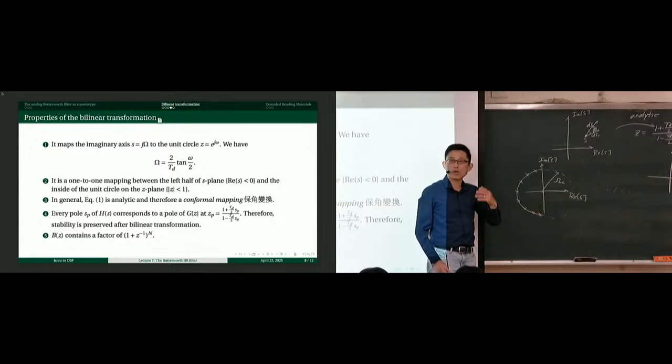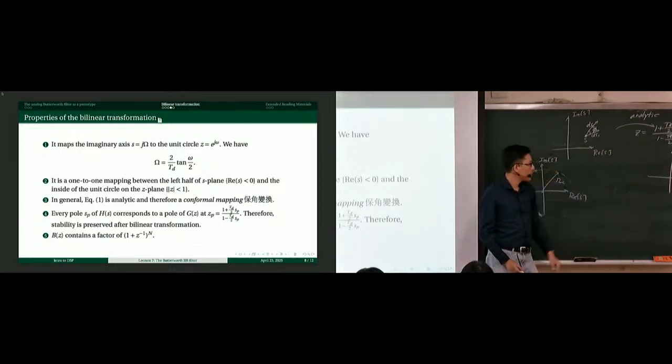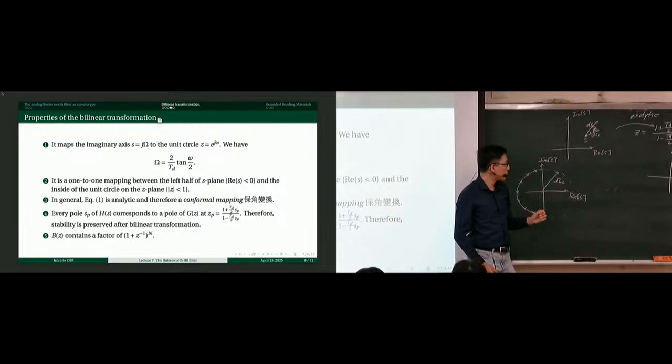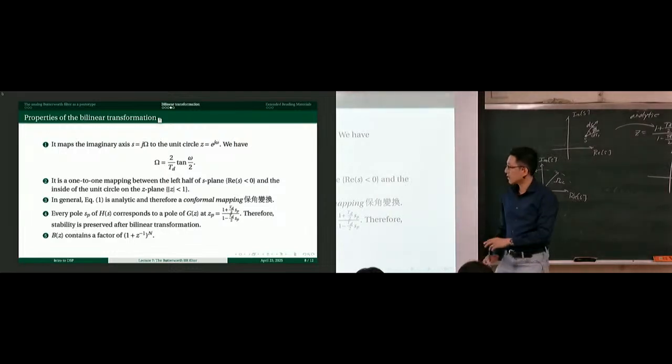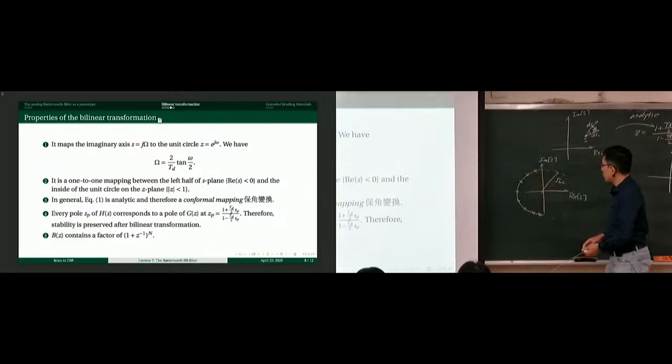This system is not going to oscillate or do anything funny like that. You begin with all the poles to the left of the imaginary axis so as to ensure stability. That's in the analog domain, the S domain. But when we go to discrete time, now it's good. It's kind of comforting. 让我觉得受到安慰啊. It's really nice that all the poles here are going to be mapped to the inside of the unit circle.